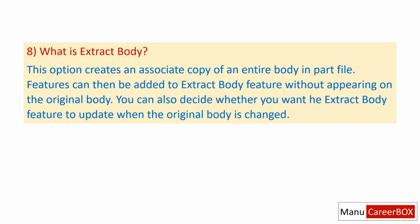8. What is extract body? This option creates an associative copy of an entire body in part file. Features can then be added to extract body feature without appearing on the original body. You can also decide whether you want the extract body feature to update when the original body is changed.